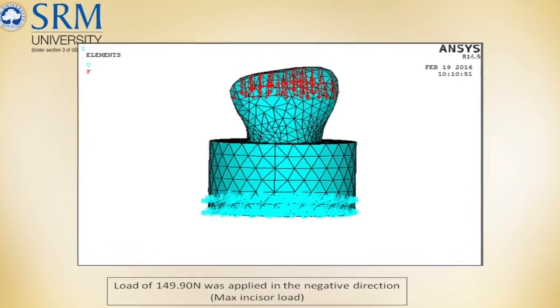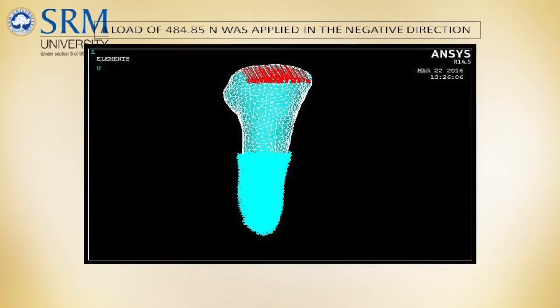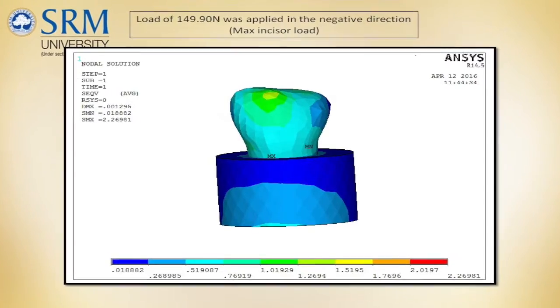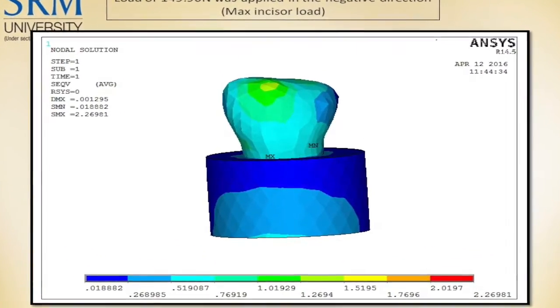Reducing the stress points is very important, because if the stress points are more, when I'm doing the finite element analysis, the maximum stress of the model will increase to a very high level, and that will probably not be accepted as a clinically acceptable model. So I did the meshing and the smoothing of the models so as to reduce the stress points. Then I applied the biting forces.